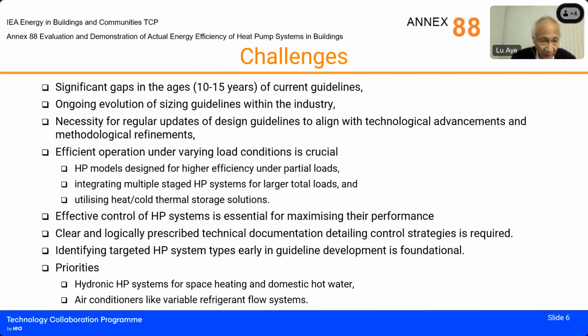Okay. Another important aspect is using multi-stage heat pumps for larger total loads. Again, it depends on your system. If we are aiming for buildings and it is a small house, it doesn't matter. However, if we are looking at commercial operation like a hotel and those sorts of things, if you have a multi-stage heat pump system, we need to think about those things.